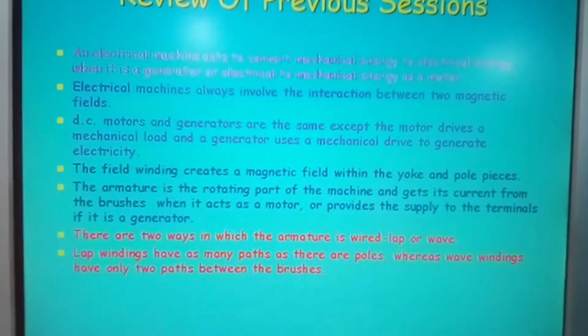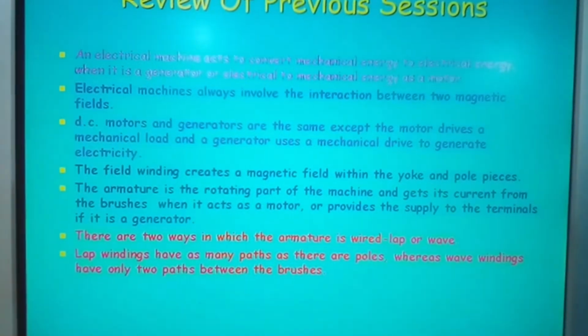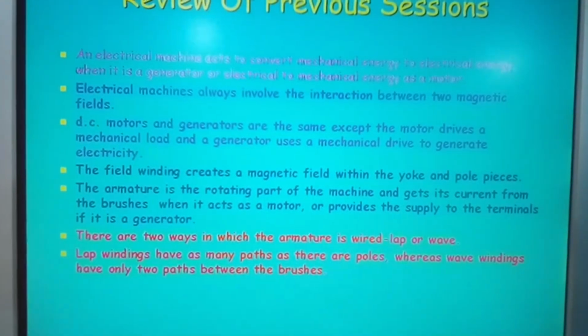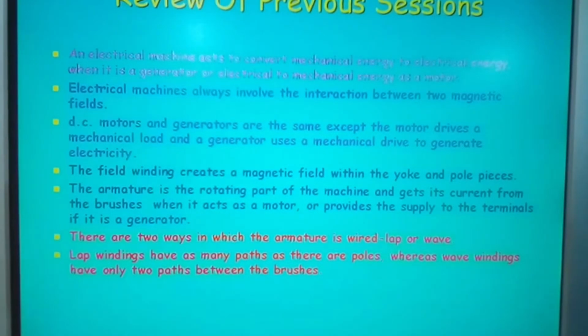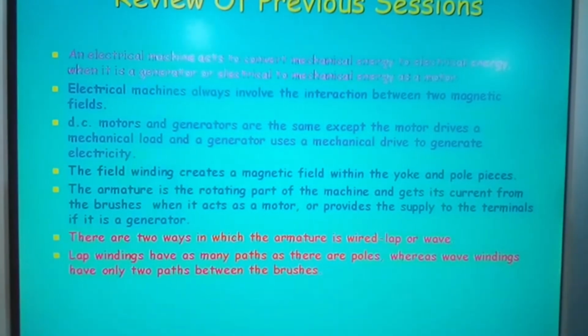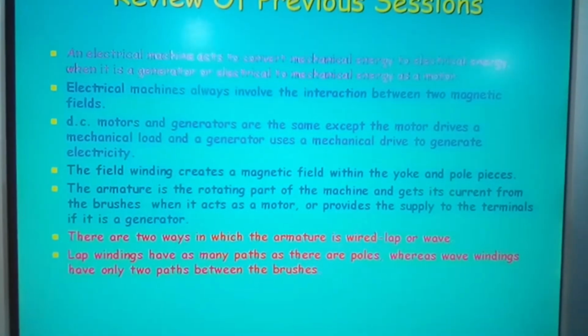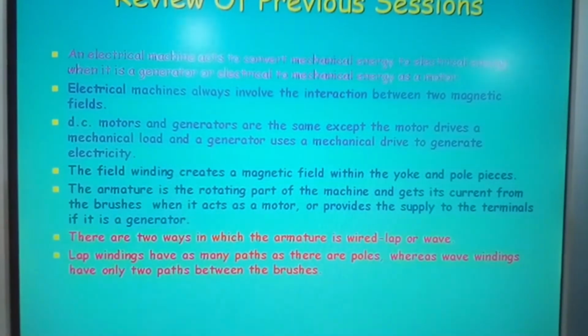And again, when you look back at this, you'll see that in regards to the wave and lap wound, make sure you've drawn up the diagram so you can identify the difference in the two. And you'll find that one is series parallel and one is simply in parallel.